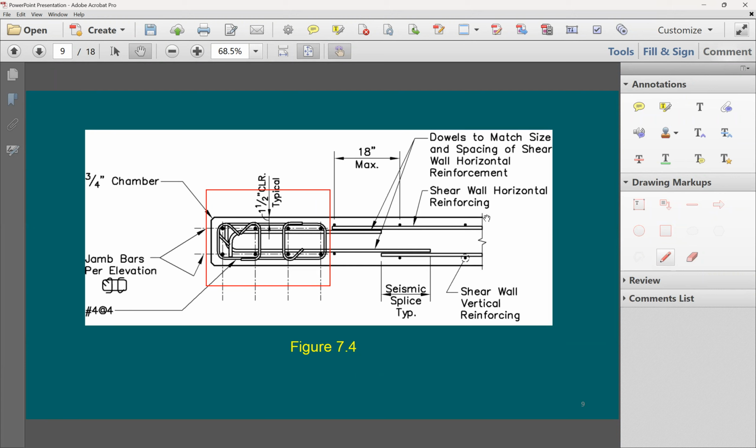Let me see how I can use this. 6 minus 2 times the aspect ratio. Here's my equation, because my value is lying between 1.5 and 2. It's actually 1.6 aspect ratio, 16 divided by 10. And with that, my shear factor equals 2.8.